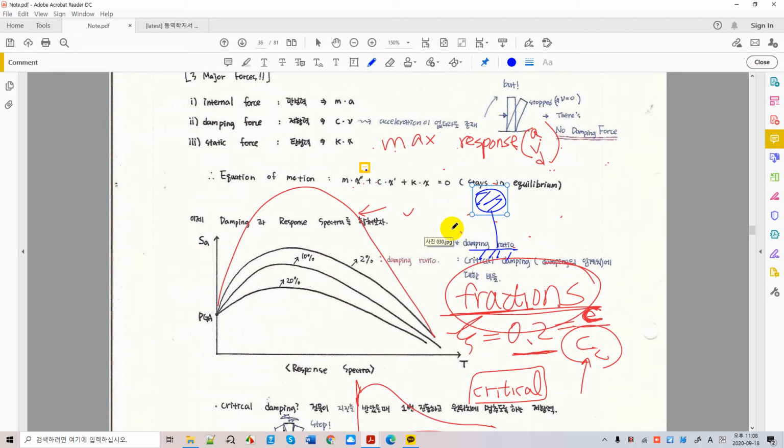So why do you need this? Because you need this in Midas input. Okay, you have two ways to input seismic load in Midas. Okay, the first way is to use a response spectra. So you put some parameters that can define the shape of response spectra in Midas.